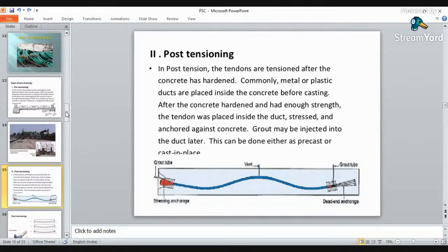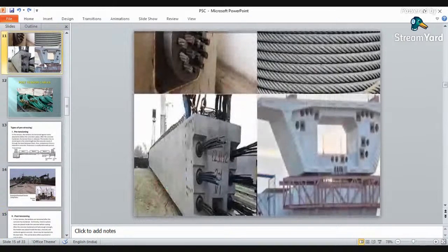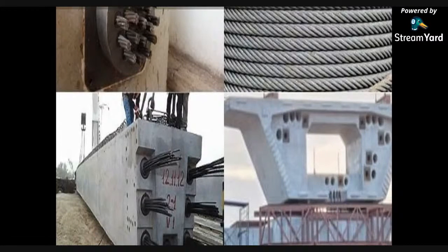Here you may see this assembly. Yes, just observe this figure. Here these are your tendons. This is nothing but your cavity. In this cavity, there will be a vent pipe or a pipe duct. Out of this duct, there will be passage of tendons. And this is nothing but your anchorage plate or an anchorage device. This plate is your anchorage device, and over here on this one tendon, there are small wedges which will fix all those tendons. In this figure, it is not actually clear.